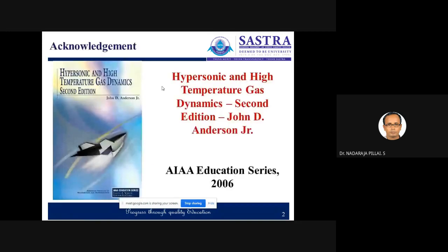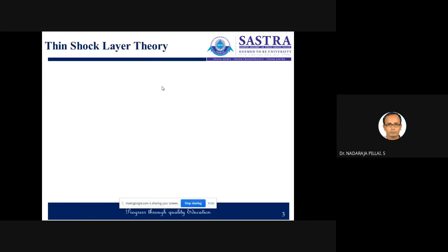I acknowledge Hypersonic and High Temperature Gas Dynamics by John D. Anderson. So let us start our discussion on thin shock layer theory. Basically, the assumption we have made is a thin shock layer. That means the shock is very close to the body, which in turn leads to a small volume between the shock and the body.